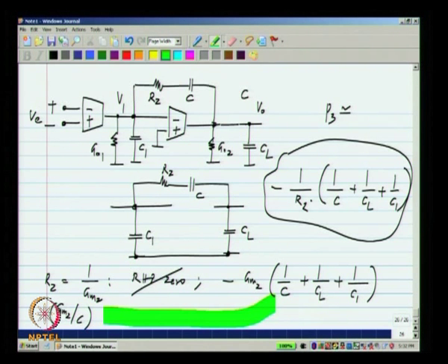Okay. So, it is not a wise thing to make RC very large, it is okay to try and cancel the RHP 0. Now, later you will also see that you cannot make component values exactly, you will not be able to make two unlike components have a relationship like this, RC equal to 1 over GM2. So, even if you nominally make it like this, it will vary in one or the other direction, but it is still a good thing, because it reduces the total phase lag that you would have got. Okay. So, it is a good technique, but do not try to overdo it, that is the message.